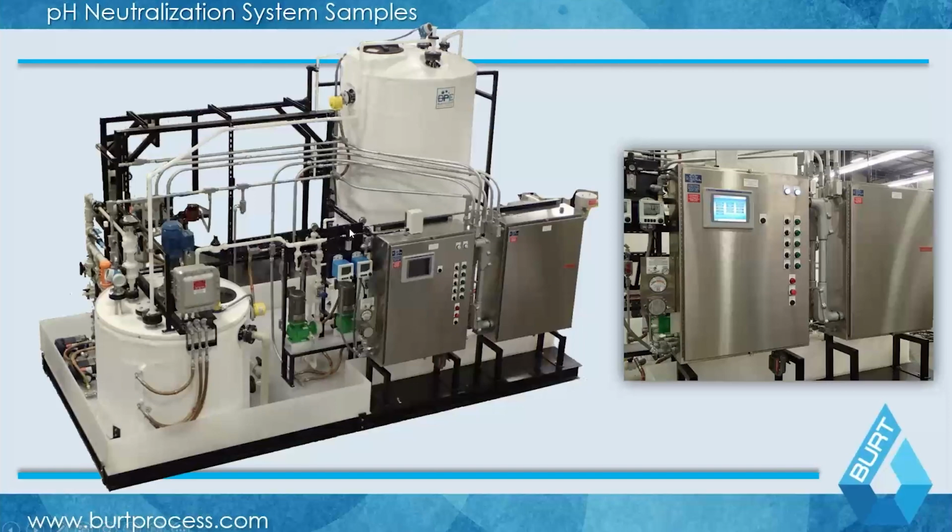explosion-proof pH systems. In this case, it's actually a batch system. You have your equalization tank, then you have your treatment tank here, and it's all Class 1 Div 2 rated. This is where you start getting into very specific applications for clients. And that's really what these are for.